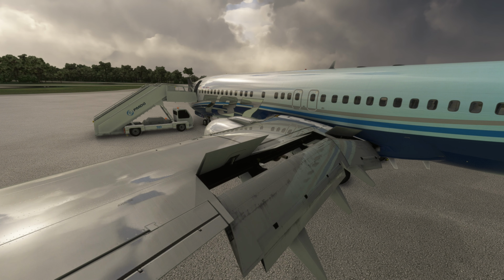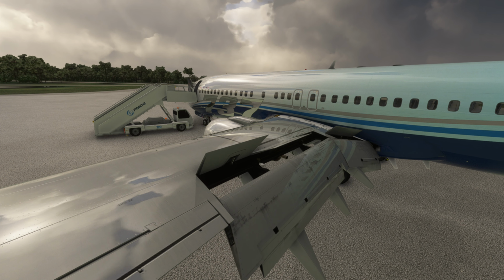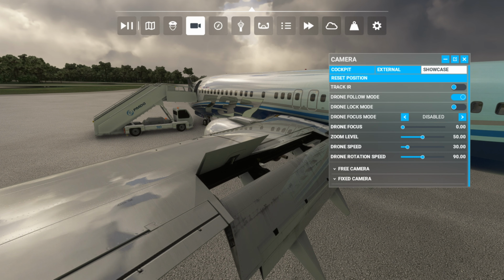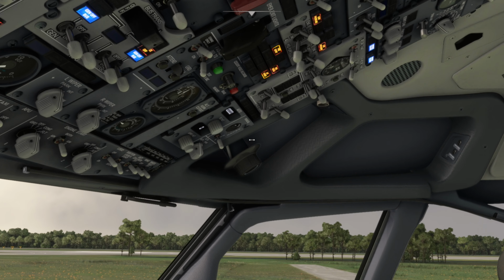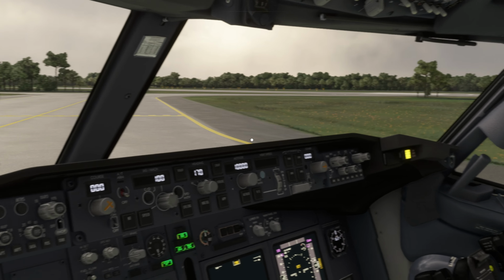On the video that has come out of Jeju Air Flight 2216, we evidently do not see the extension of the leading or trailing edge flaps and slats, which means that the airplane is going to have to maintain higher speeds in order to maintain flight. This is also going to necessarily require a higher landing speed, which is something that we also see.